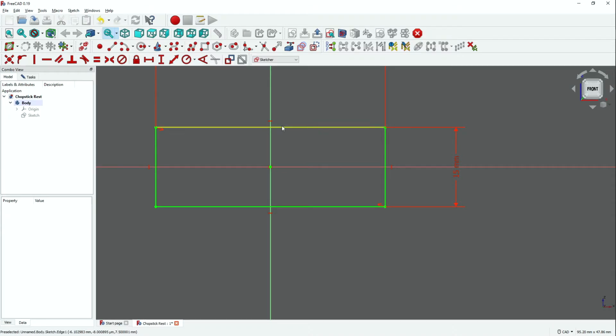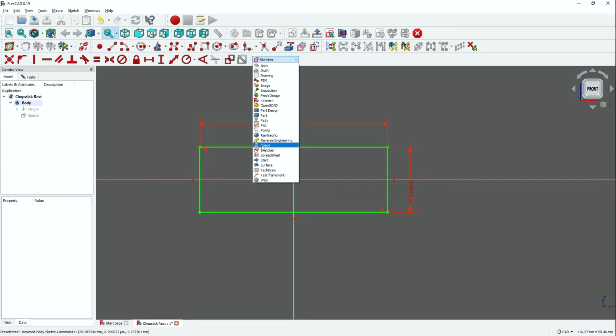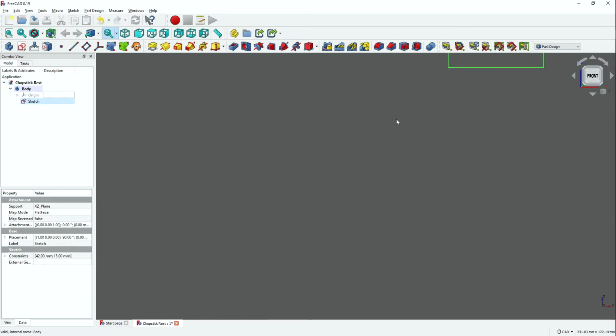So now, what do we do with this 2D shape? If you're new to CAD, we use these 2D shapes generally to create 3D geometry. So we want to go from Sketcher, which would be like on a piece of paper, to what they're calling part design, which is now like, imagine an artist who's going to use this as instructions. In software like SolidWorks, it'd be extrusions, but here they call it pad.